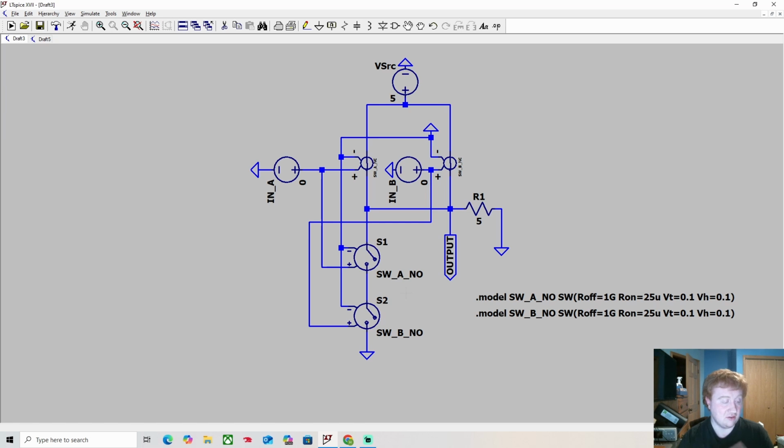Those are for BJTs really. Technically MOSFETs have a voltage bias as well, but it just acts different. And for the most part, when you're talking about digital logic, you don't really consider the 0.7.